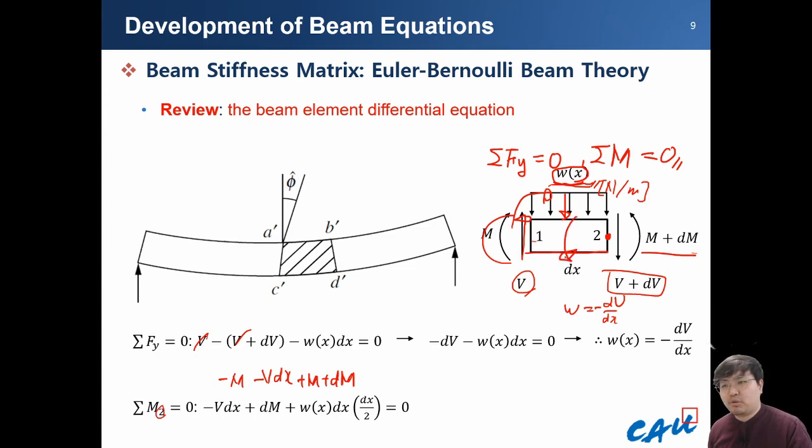So how can you obtain this? Those kinds of distributed forces can be replaced by some equivalent force. The total force is equal to the integral of w dx. Maybe the center point, the middle point, can be the equivalent point. It is because all points generate these forces, each with its moment arm.